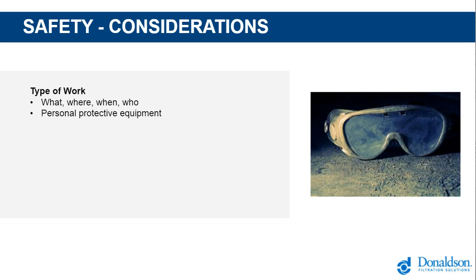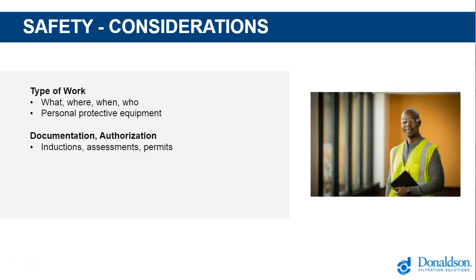Then we lead on to documentation and authorization. Considerations really there are for being inducted for the particular site that we're working on, any forms of risk assessments and method statements. Is there a permit required to carry out that work, and has it been authorized and signed off? And do we have the necessary certification in place?